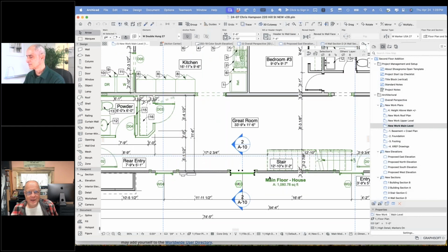If they have to subtract the drywall or the exterior materials, they're going to make some mistakes and not be able to work it right. So I focus on that here, and in other views I show the full layers, particularly the sections and so forth, so you see how it all goes together. You don't have a plan view that has the full composition of the walls.